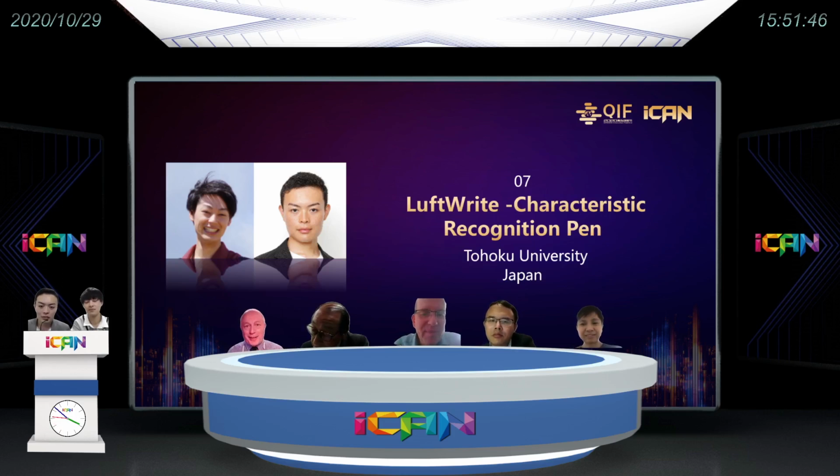First, unmute myself. Very nice project, to make your pen to write in the air. Now you have used the MPU 6050 module together with your STM32 microcontroller. This MPU 6050 has an accelerometer, but it also has a 3D gyroscope. If you want to derive position from acceleration, you have to integrate the acceleration two times.